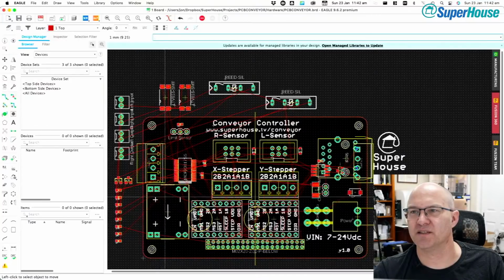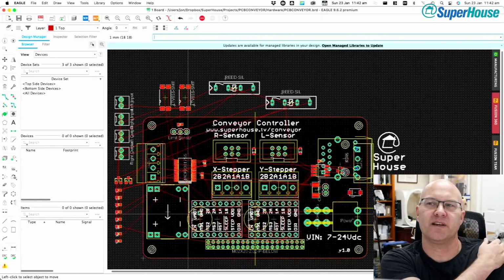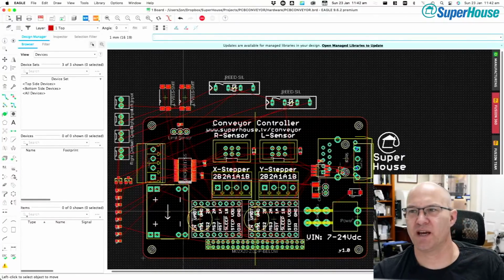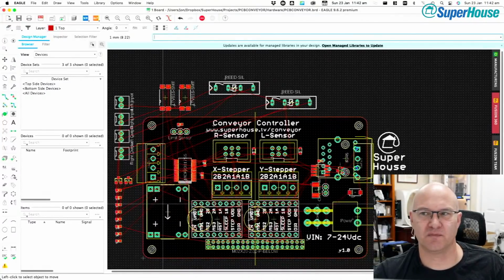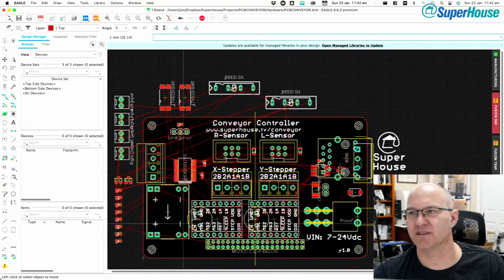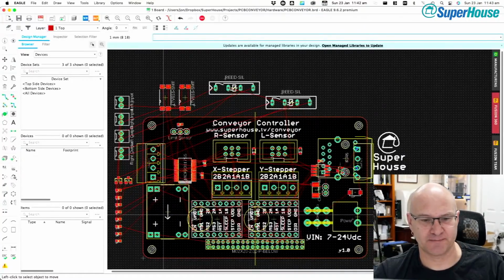This is the voltage regulator module. As a starting point, I just slapped down an off-the-shelf regulator module. It's 5 volts, 3 amp rated. I've used these in a few projects, and they seem to be generally reliable despite being super cheap. So, I don't know, that'll do. The only thing this is powering is the ESP32 anyway, like the screen and stuff. The loads aren't being powered through this, it's just the logic.